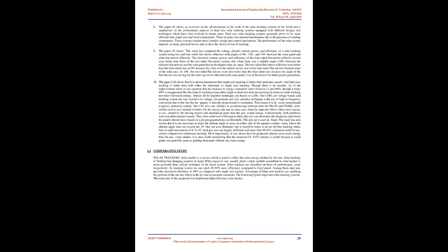During all months the tracking panel presented irradiation gain over the fixed panel, ranging from 17.2% in June to 31.1% in November. At the end of the period of analysis, the period being a total of 152 days, the tracking panel obtained an average gain of 23.4%, considering the proportion of rainy or cloudy days as 40%.